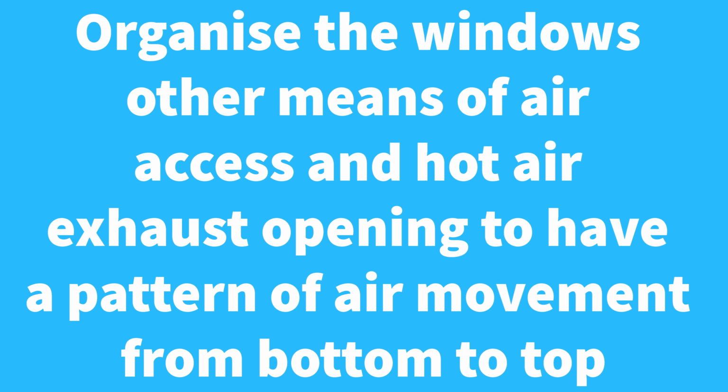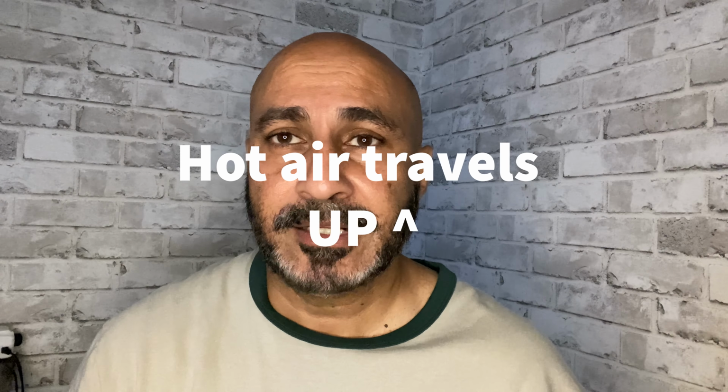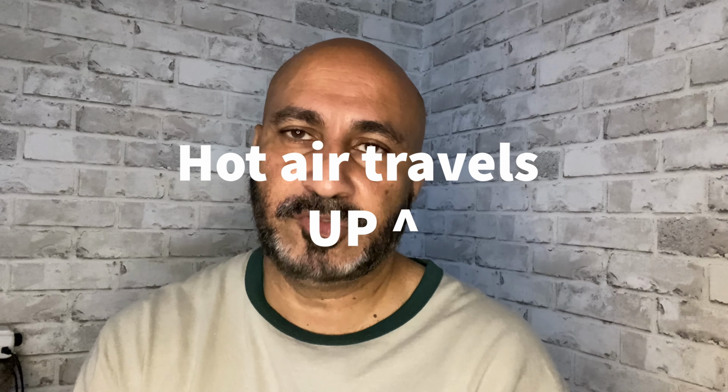You do not fully open all the windows on the top floor, and maybe you control the closure of all the windows on the top floor, and probably increase a bit the ones from the bottom, so that more air will come inside, more air displacement will take place, more air changes will take place, and this will also control the movement of buoyant air or lighter air towards the air well, so that air changes can effectively happen. So when we understand the natural ventilation system, we know how to make use of it to our benefit.